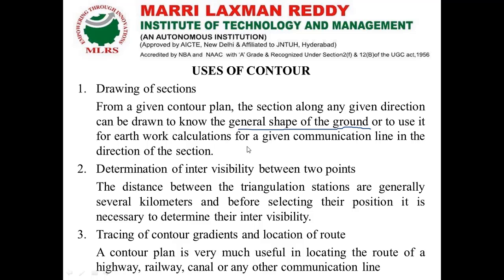reaches. Second one, determination of intervisibility between two stations. Here the triangulation stations are generally placed several kilometers apart. So before selecting their position, it is necessary to determine the intervisibility between them. Then only will our work progress be easy for us.